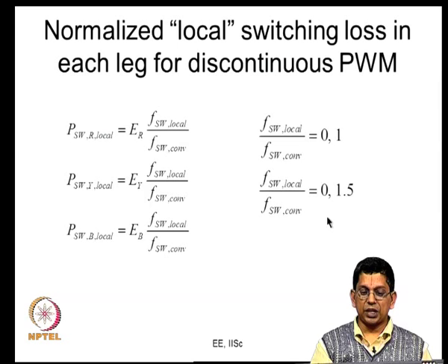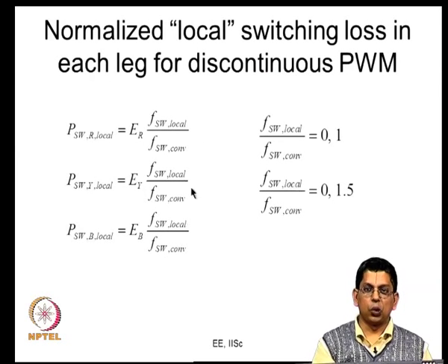So, the switching frequency of a particular device, if you look at, is 3 kilohertz for 120 degree duration in a half cycle and 60 degree in another one. So, we can call the term average switching frequency. The average switching frequency is only 2 kilohertz now. The devices actually switch only 2000 times in a second, though the carrier frequency is 3 kilohertz. So, the average switching frequency is low.